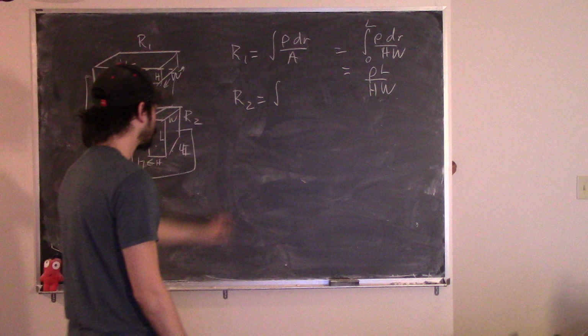So what we can say is that we have 2 equations. V is equal to I1 R1, and V is equal to I2 R2. We have different resistances and different currents, but the battery is the same. This is the same V in both cases. Which says then that I1 R1 is equal to I2 R2.